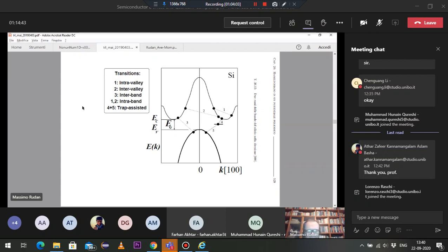And you remember that we anticipated that if the electron belongs, for instance, to this position along the conduction band, and there is an external perturbation that is a weak perturbation, then this dot moves along the branch, indicating that due to the external perturbation, the energy and momentum of the electron are changing. Okay.